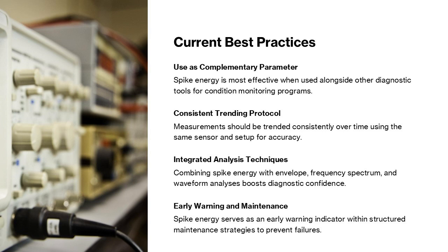Best practice dictates that spike energy measurements should be trended consistently over time using the same sensor and setup. Absolute comparisons to legacy severity charts should be avoided unless sensor equivalence is verified. Engineers are encouraged to combine spike energy data with advanced techniques such as envelope analysis, frequency spectrum analysis, and time waveform inspection. This integrated approach improves diagnostic confidence and reduces the risk of false alarms. Spike energy can serve as an early warning indicator that prompts further investigation using more detailed analysis methods. When applied within a structured maintenance strategy, it continues to provide value despite its age.